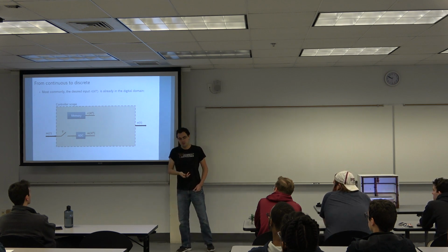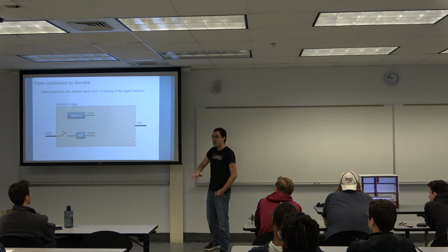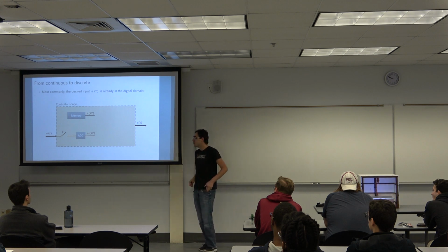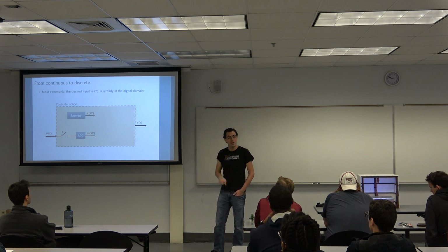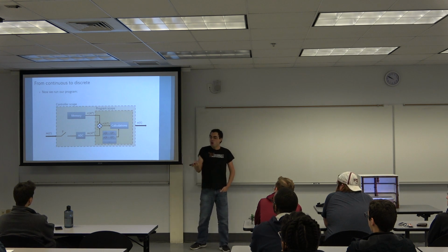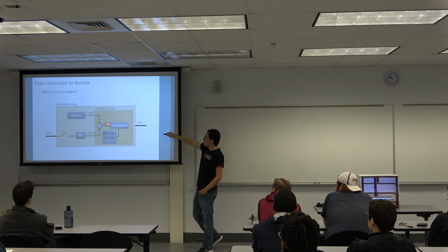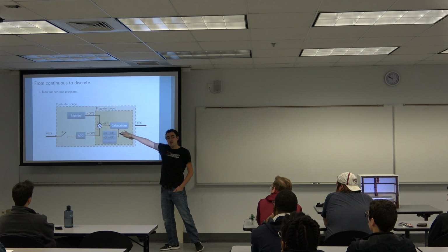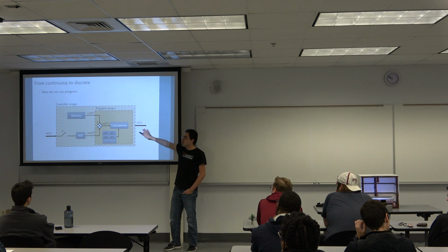And this is the case even if you don't have something hard-coded in your code, you can have the user just type in a number on a keyboard, and that's going to go to the memory. It's not going to be an analog signal. Right? So it makes sense to replace this block with a memory block. And then we perform our computations. So the computation includes computing the error, and then doing some calculations. We can use past values that we can store in our memory. We perform some calculations, and now we want to come up with a u of t.